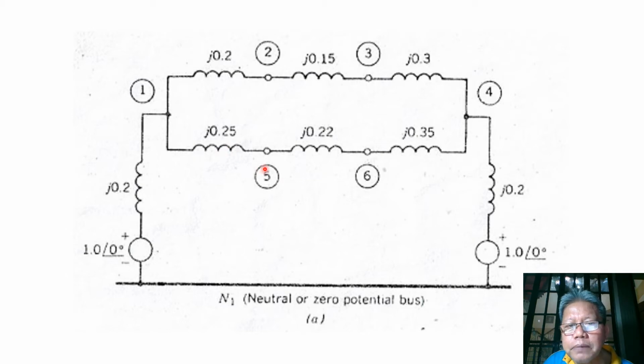And between bus 5 and bus 6, we have a transmission line TL56 with its reactance of 0.22, and the resistance of the line is also neglected here. Now, between bus 6 to bus 4, we have transformer 4, which is delta-delta connected, but the positive sequence current can just flow from its primary terminal to the secondary terminal. So this is how we represent our positive sequence network.